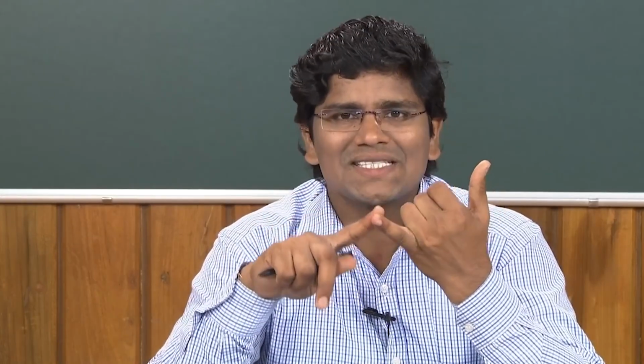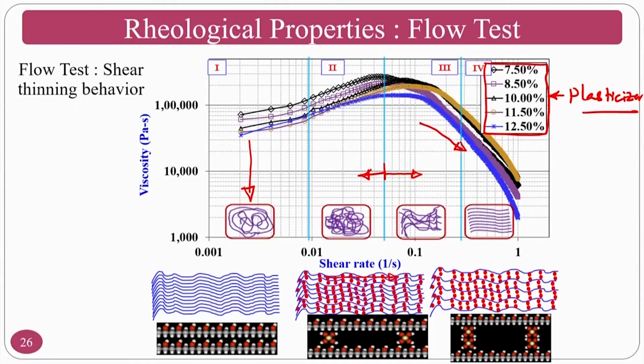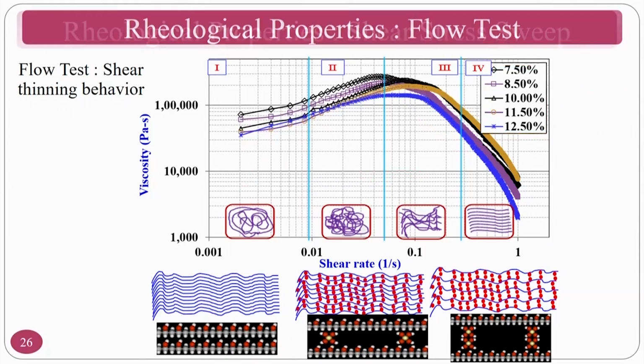That means you are imparting viscous nature, because the plasticizer, softeners, all these rheological additives dominate in viscous characteristics, and the base polymers dominate in elastic characteristics and partial viscous nature. That is why the viscosity of the medium will reduce.